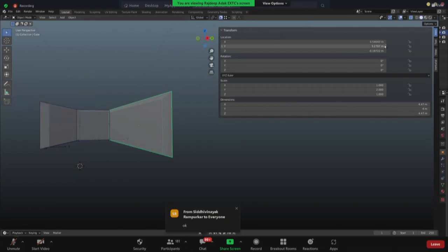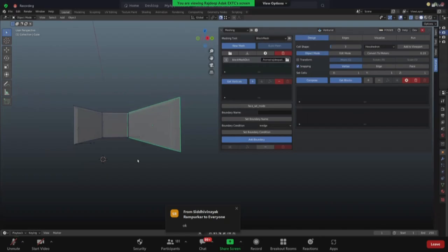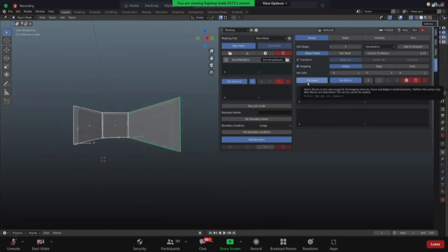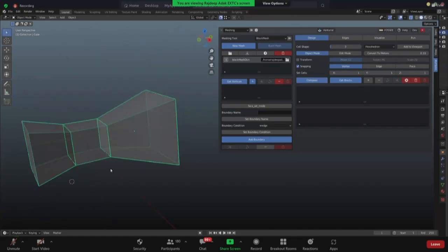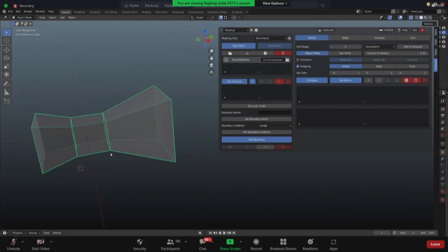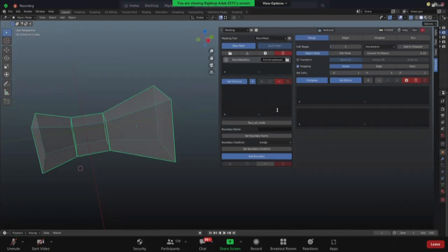Okay. Now once we have done this, I'm going to select all of them together. Okay. And then I'm going to press the compose button. Okay. So compose button is what removes all the vertices which are repeated, and it removes all the faces that are also repeated. And it creates a singular geometry form. Okay. Now you won't really see any change per se, but if you try to move this block after pressing G, you won't be able to do that. That basically means that you have locked this geometry. Okay. Now all I need to do is query information out of it.